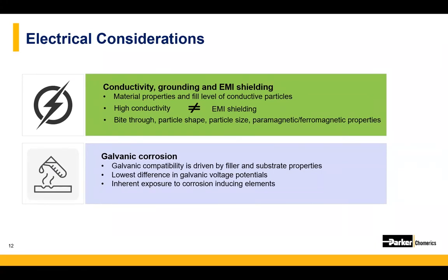However, across most frequencies, a nickel-plated aluminum particle will have a higher EMI shielding level than a silver-plated aluminum because of the inherent absorptive properties of the nickel. So Ben, does high conductivity always lead to high EMI shielding? It certainly does not.